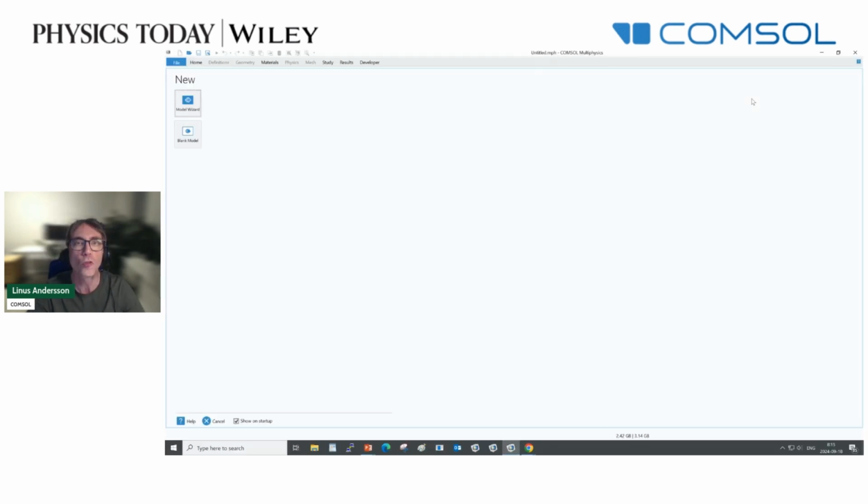To get the model started, let's now switch over to COMSOL to set up and solve this equation for the velocity potential. So here's COMSOL, a mostly gray window, but that's soon about to change. The first thing we're going to do is walk through the model wizard, in which you're making a couple of choices that will lay the foundation to your model. So space dimension, well, it's going to be 3D, of course. Note that we have planar as well as rotationally symmetric 2D, 1D, and also 0D.